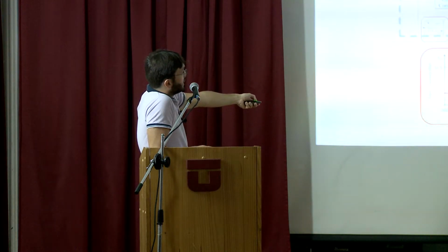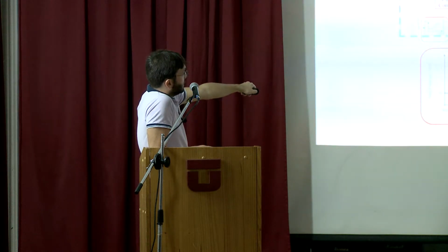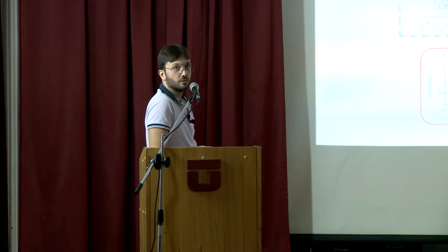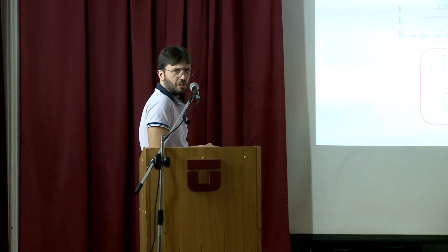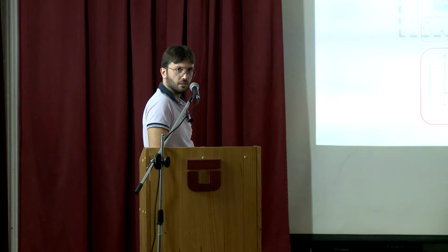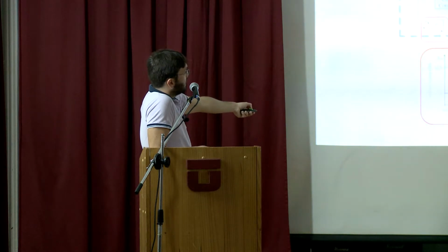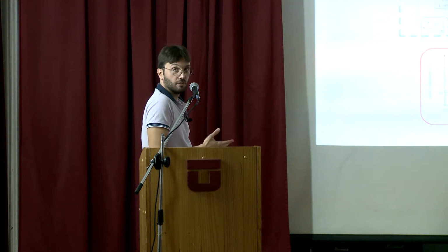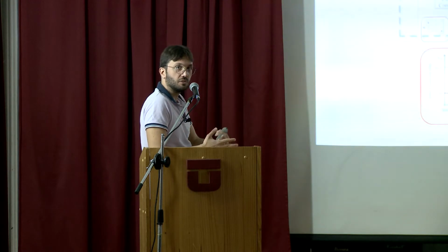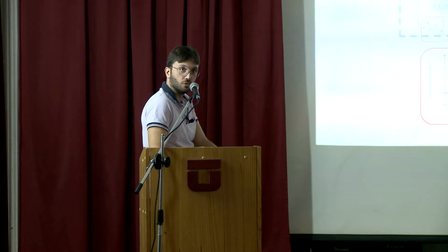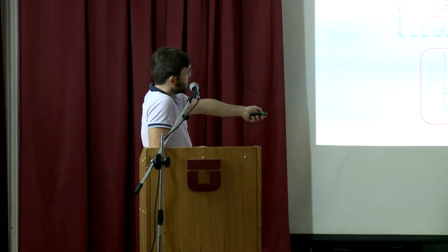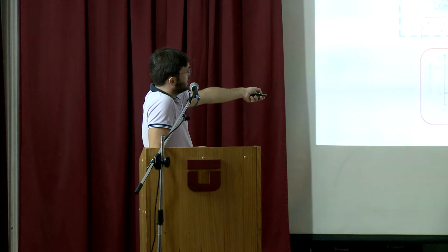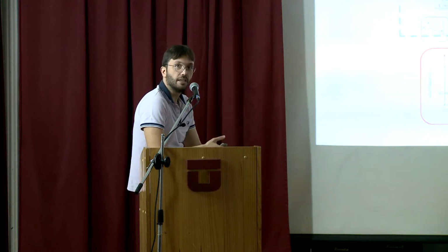And this is what I was talking about. With the time regulation, the maximum frequency is 51.5. Across Europe, they have similar values, 51, 50.5, 51.5. And the derating starts from 50.3. So there is this dead band where the frequency is allowed to fluctuate. Then, if the frequency increases, the converter has to curtail the power.